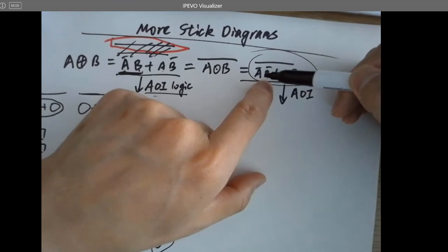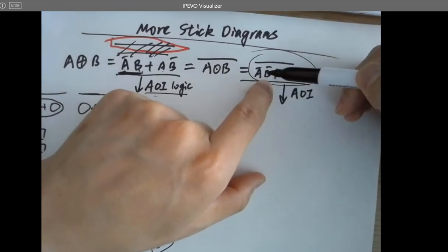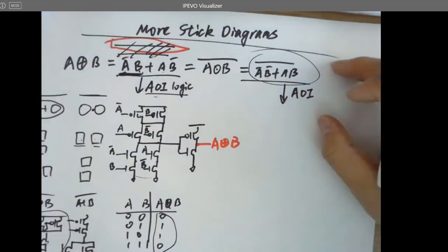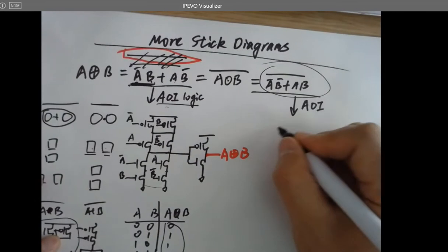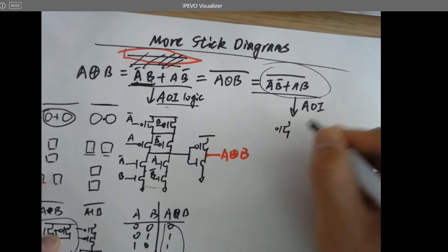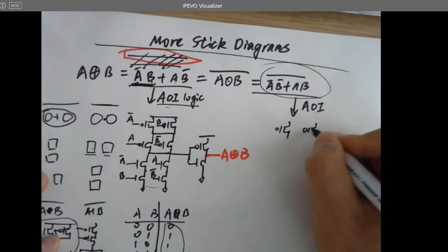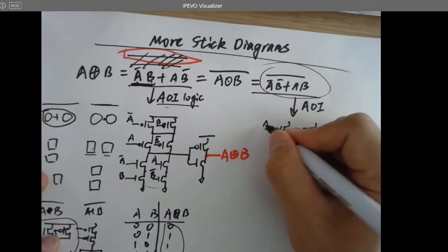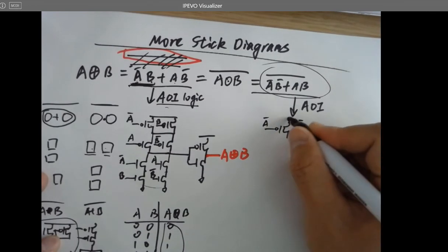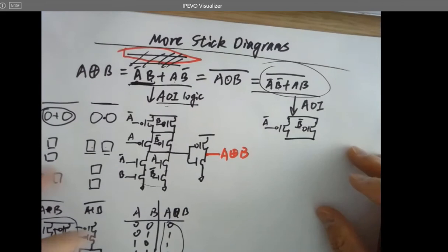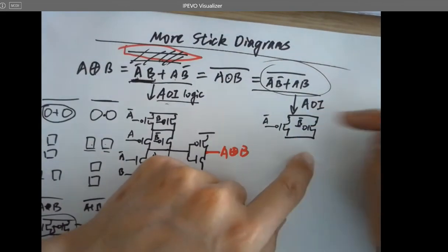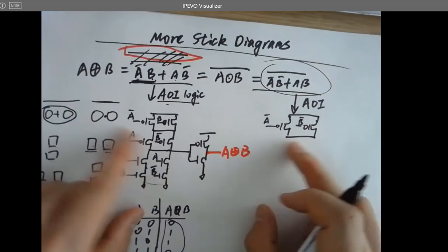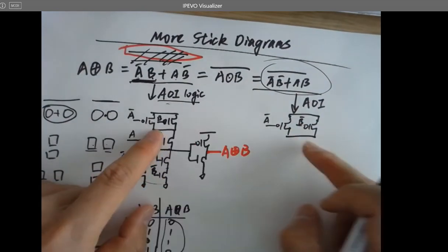It's an AND logic. AND, right? You want to think about the non-logic here. So the two PMOSes are in parallel. So you're getting A naught, B naught in parallel. You want to close these two terminals at the same time, on the top and at the bottom as well. So if you compare here with this one, what's the difference?